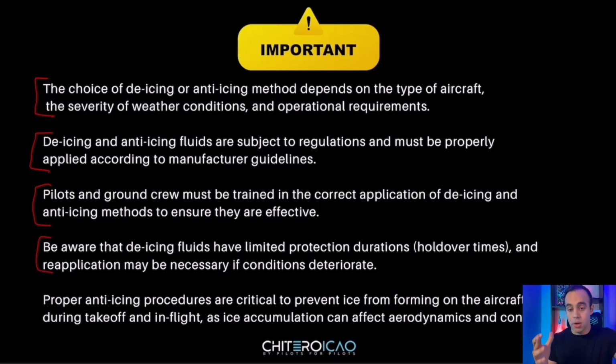After that, we need to be aware that de-icing fluids have limited protection durations, which is the holdover time. We're going to talk about this in 1 second. And reapplication may be necessary if conditions deteriorate. What is that? So after I apply the fluids, they're not going to be there forever, right? So we're going to talk about it.